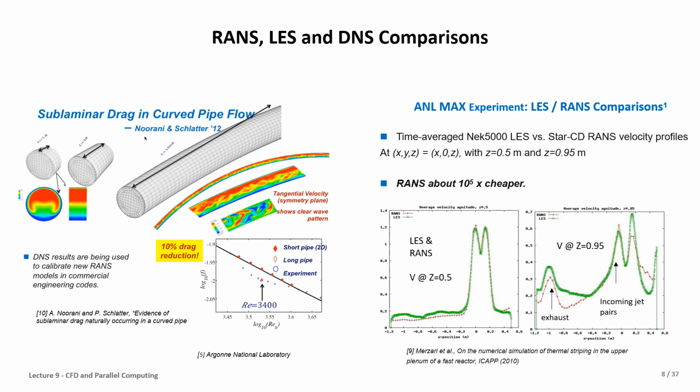So in this slide, these two examples present the capability and the result of RANS. However, it seems that, rather than accuracy, sometimes RANS is not able to cover some information of the problem domain. And it's always required to check the result, especially with the experiment if possible, or with LES or DNS.